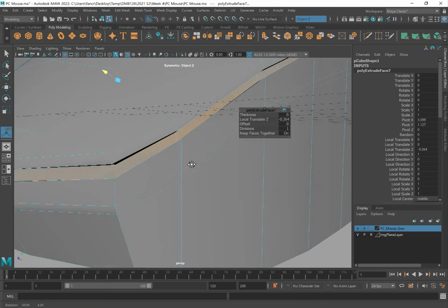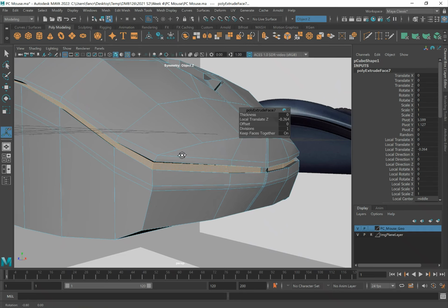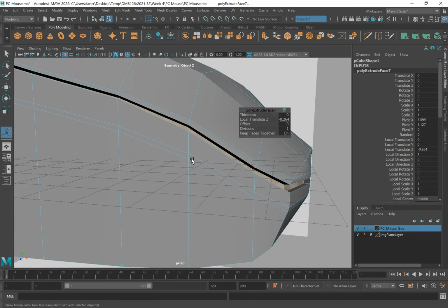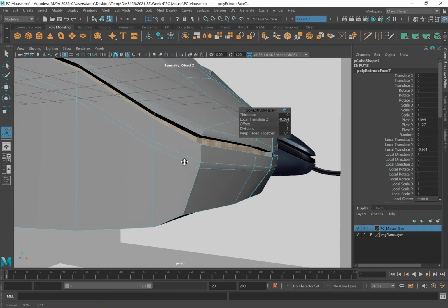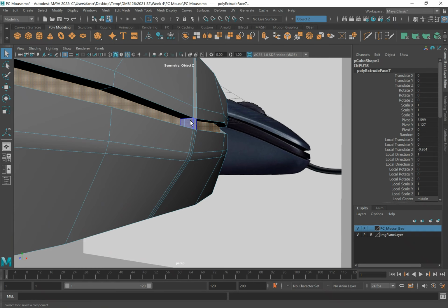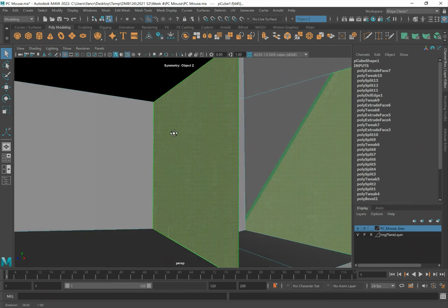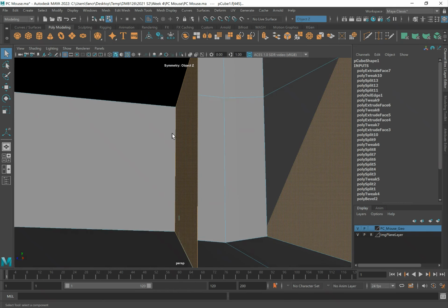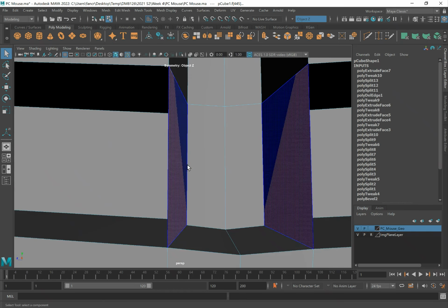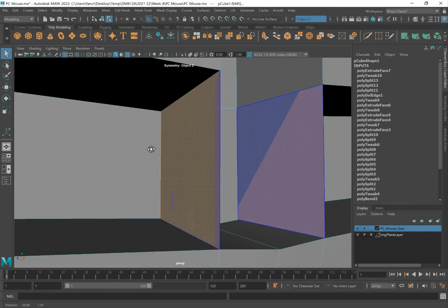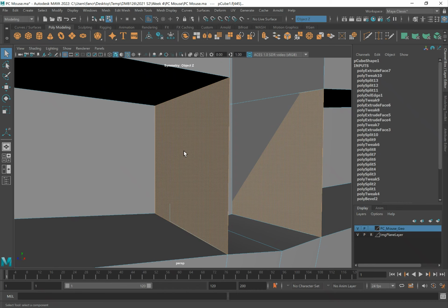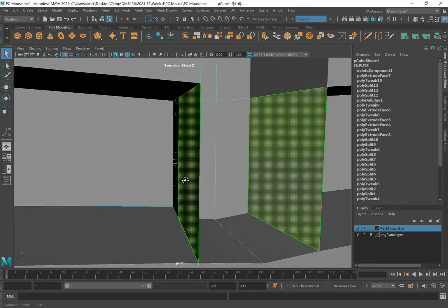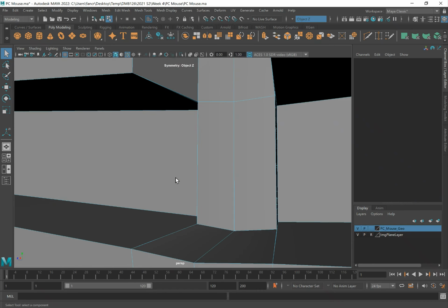Again, I'm not too worried about it because I can potentially fix that. Once I have created that, the next thing I would want to do is select this piece here. This is what we call overlapping faces. You can tell that half the face is being displayed. So I'm just going to remove it by backspace, and select this piece as well and backspace.